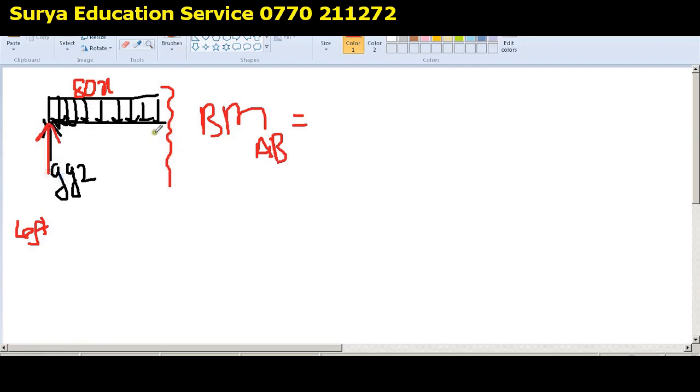Understand? So now, because of this vertical reaction force, when you consider this as the pivot end, something like that, this is the pivot end fix. So now this will give the moment like this. The left side will go up, so it is positive bending moment, because otherwise you don't know how it is defined as positive. So that would be 992 multiplied by the distance. Guys, what is the distance? It is x, so 992x.